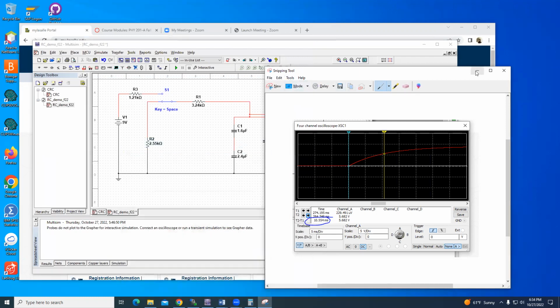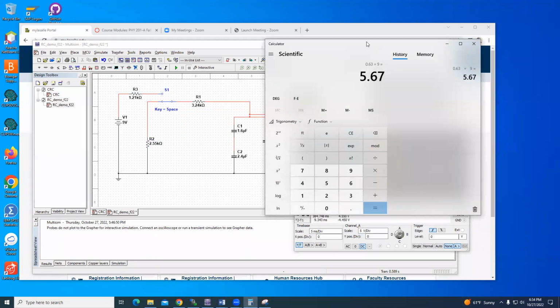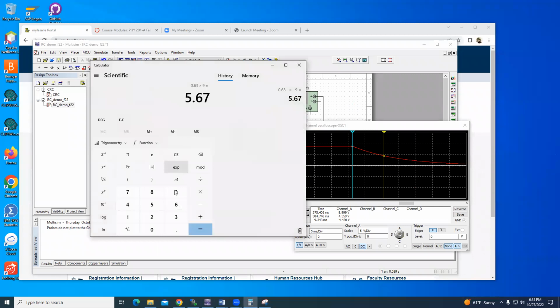And then let's find, oh, that's the picture, and then I need to do the down. So find the corner again. So here I am at 8.999 and see when it changes. Okay, it started to change. I'll go back to the corner. And now going down, I want it to be 37% of the saturation voltage, which was 9.